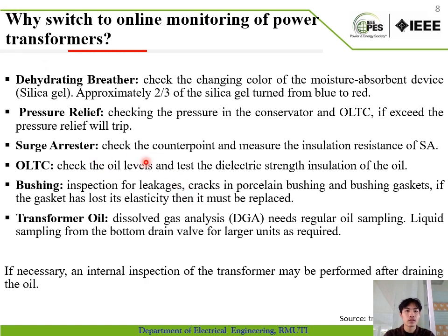And with the online system for the bushing, we can monitor the capacitive and resistive leakage current, and we can analyze the current in the power curve too.